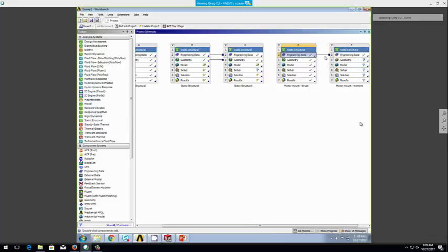So we need to make some assumptions and have data for our aircraft available to form it. We will form an initial maneuver envelope with the design speeds for your aircraft, and then we'll complete the VN diagram with a gust envelope.